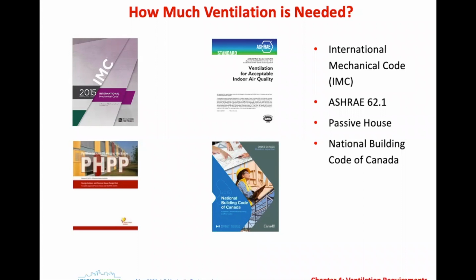Those are set by the local jurisdictions. They reference in the International Mechanical Code, ASHRAE 62.1 is typically the basis for it. But in your local jurisdiction and by state generally, they may adopt ASHRAE 62.1 and the International Mechanical Code entirely, or they may have some exceptions. They may not adopt some of the metrics that are in that code locally.